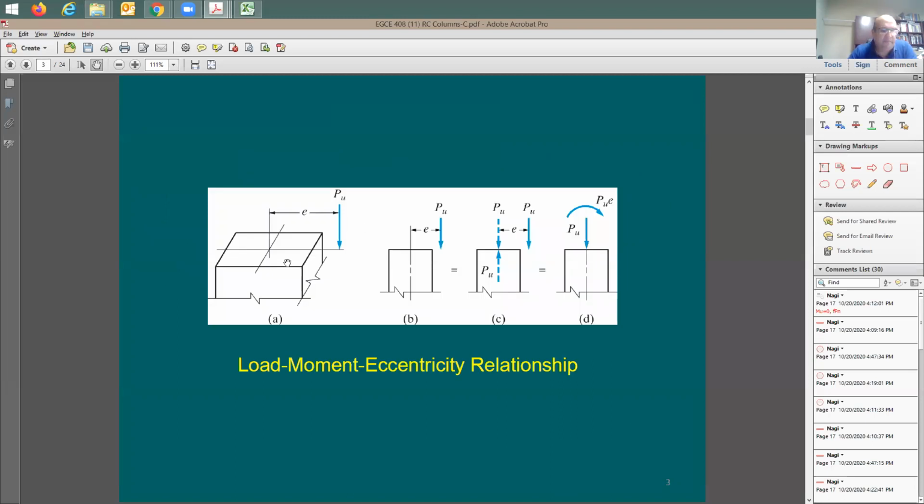So here's a column, like in 3D. The column usually is going to be exposed to an axial compression force. It's going to have some eccentricity. This E indicates eccentricity. When you look here from the side of the column, you see that you are going to be rotating the moment about an axis that runs perpendicular to the screen, which means this axis, correct? This moment is rotating about this axis.